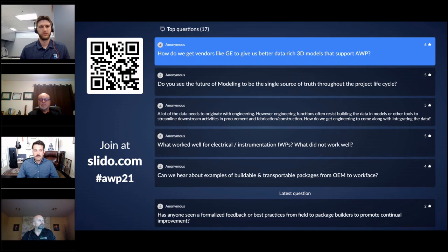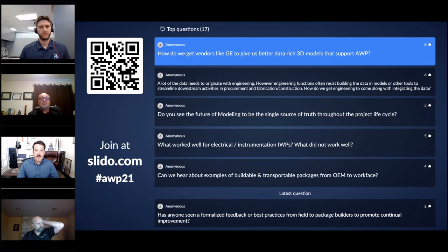You also need to consider what data needs to be in the 3D model. Here it says a data-rich 3D model. So I would, again, maybe go back to the BIM uses. How are you going to be using this 3D model? And that drives how the 3D model is developed in terms of level of development and how it's broken up, but also what data needs to be in the model.